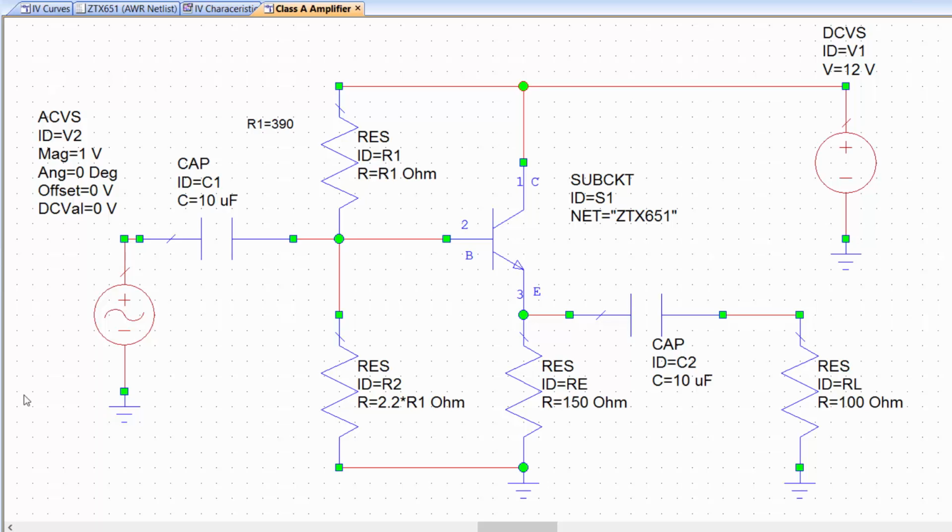The fact, however, that we have the same voltage but different currents means that, impedance being voltage divided by current, this amplifier acts as an impedance buffer. It can transform a high impedance into a low impedance.